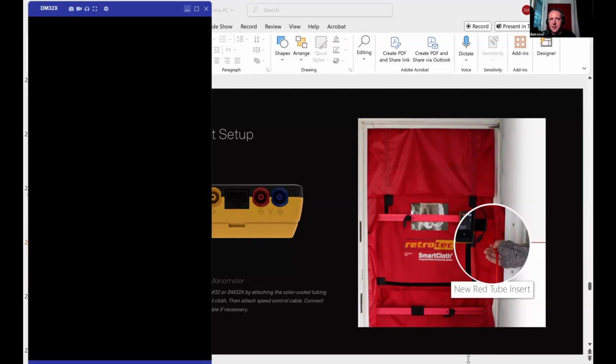Usually what I like to do is pressurize. I think it's easier to watch it go away. And so if you see that fog just shoot up into the attic, it's a leaky attic that shouldn't be. So that's just a quick check, and then you can go from there to see where those leaks are.